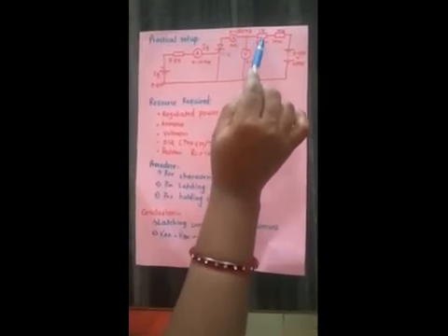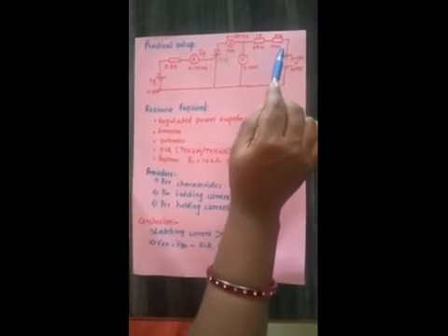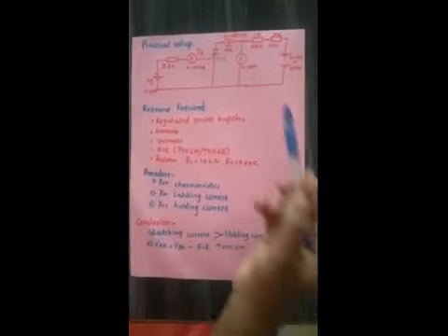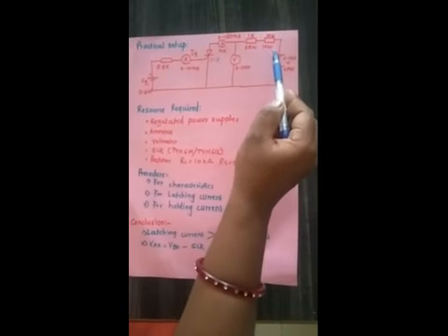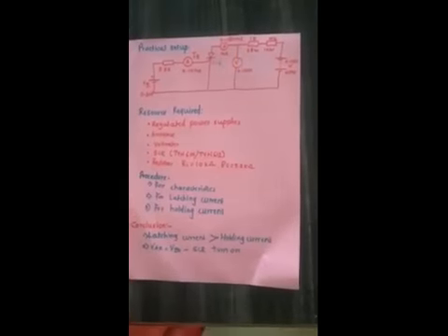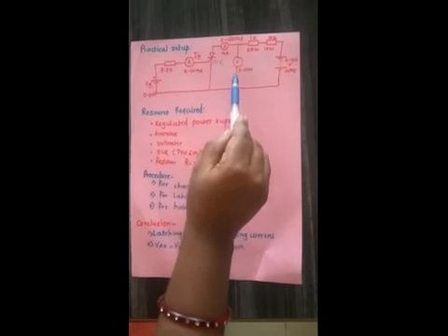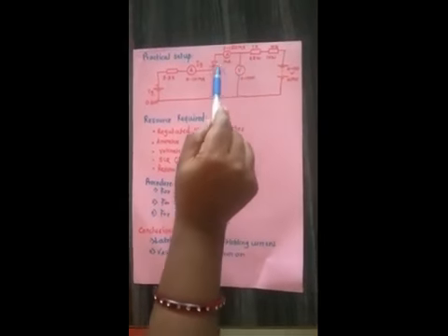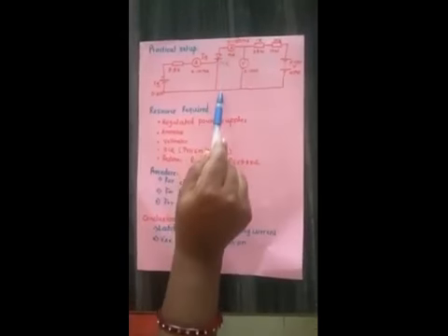And also after that a 1 kilo ohm resistor is there. After that a 10 kilo ohm resistor is there having different wattage. It has 2.5 watt and it has 10 watt. Now parallelly I will connect the voltmeter V to measure the anode to cathode voltage. It will be exactly parallel to the SCR to measure voltage between anode to cathode.